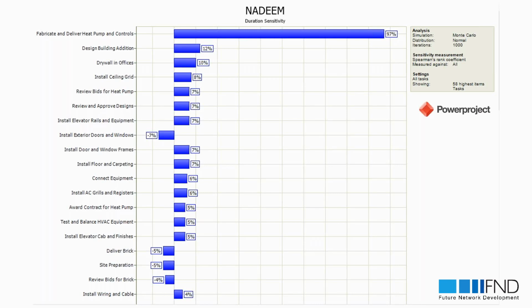The 100 days activity has, let's say, 10 days, or 2 days total float. Our first approach, first focus, is critical activities. Because this is critical, we have to focus on it. But we always know the critical path can change during the project schedule. That's why we need to focus not only on critical activities, but also activities which can be critical in the future because of the performance, because of the logic change.